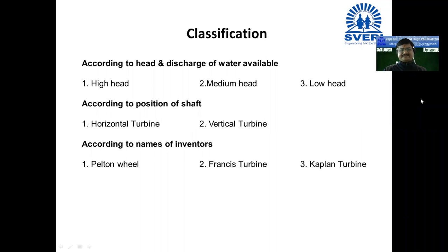According to head and discharge, according to position of shaft, and according to name of inventors. According to head and discharge: high, medium and low head. According to position of shaft: horizontal and vertical. And according to name of inventors: Pelton, Francis and Kaplan.